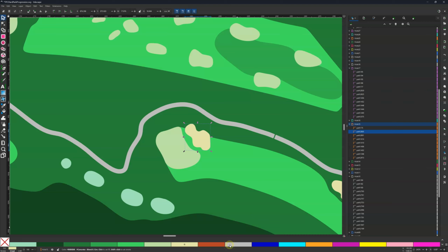You say, oh, I don't want blend on my cart path. You don't have to, actually, the blend will be there, but you don't have to make it a blend. You could just make it all the concrete material from in to out, and then it doesn't blend to what's around it. But there are some tricks to actually make concrete blends look really good. But that's a little advanced topic. So here's our water. You can see blend of 12 centimeters on the outside and 18 centimeter inset.